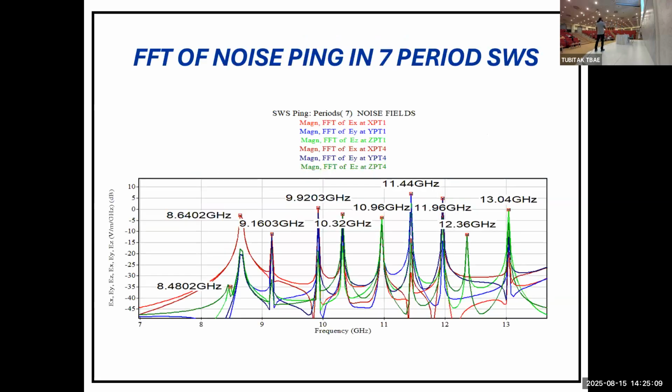So the first step, always, when we are trying to design a high power microwave device, is we start with the cold test. We just ignore our beam for a second and start optimizing our structure with no electron beam. This is the first step. I showed this yesterday. Do you guys remember what we are doing here for our structure?